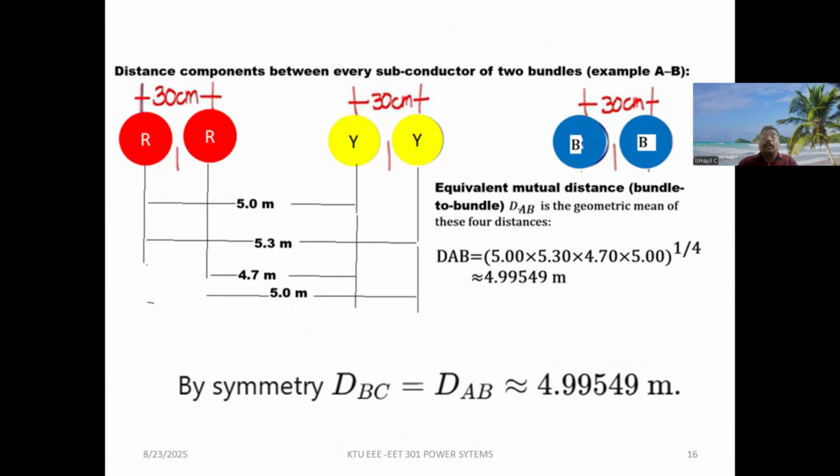Minimum, it will be 2 distances. There is no case. And in 3 distances, we have to find out the cubic root. And for n distances, we have to find out the nth root, or we have to multiply all those distances raised to 1 by n.